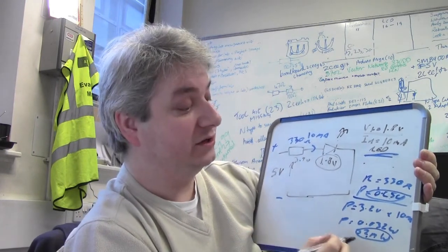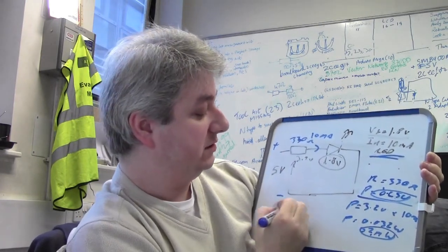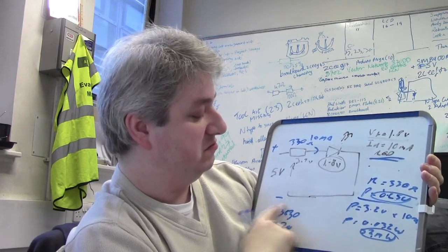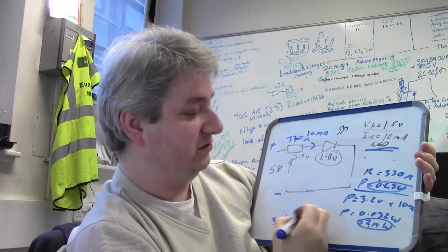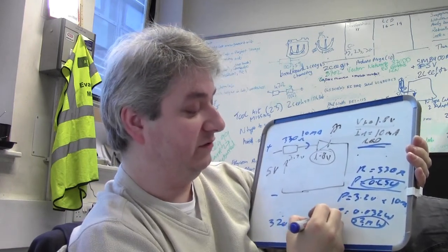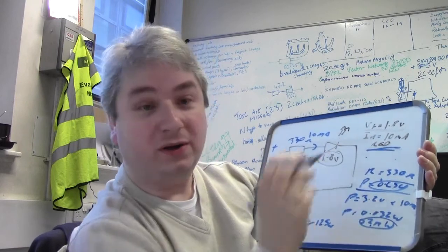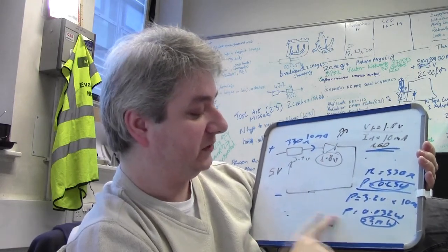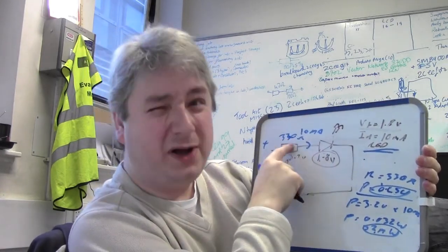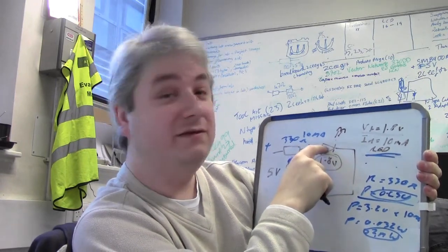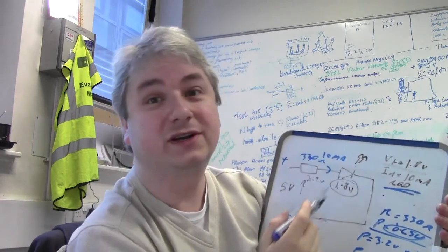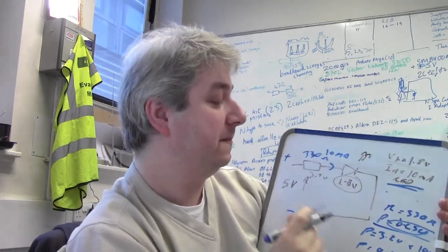That's what you need to go for. So if you needed to purchase a resistor, you need a 330 ohm or 320 ohm minimum, and something around an eighth of a watt, 0.125 watts. You could even go lower if you really want to. As you can see, the power dissipated in this resistor is very little. Everything is going into this LED. LEDs are really efficient, that's why. Even with your resistor in there dropping excess voltage, it's not too bad.